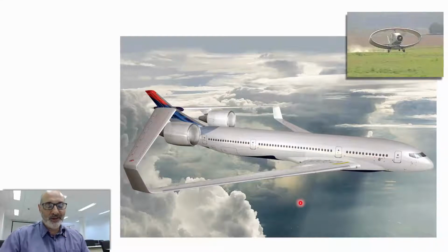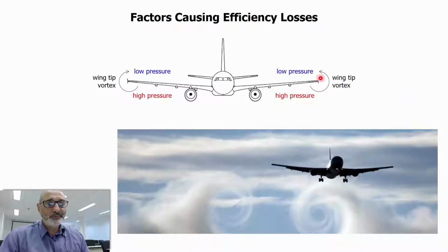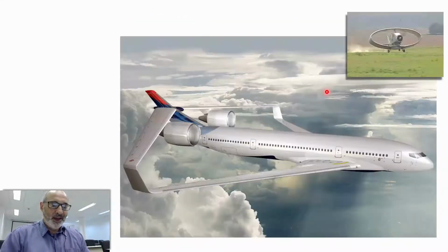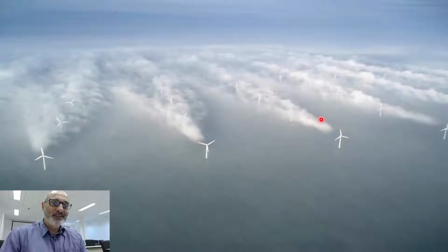Just to show you, in aeronautics engineering, to solve this problem, the engineers developed these small structures here, called winglets. They developed this kind of device which generates an opposing effect, so they tend to cancel this vortex, but they cause drag. So it's a trade-off solution. Another possibility: if the problem is at the tip of the wing, let's build a wing without a tip. You build this kind of structure here. This is very optimistic, I should say, but there were some models that were built, and you can see this in windmills. This kind of turbulence, you can call this turbulence.